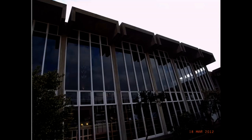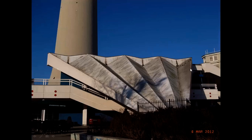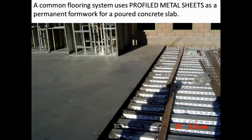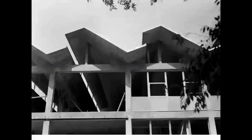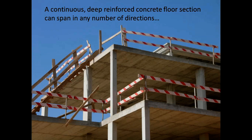So finally, all of those, as you can see, again, these are linear structures. This is spanning from one side to the other, and it's just repeated, repeated, repeated, as was our structure back at our university. If you want to build a roof and you can't necessarily take load to ground at very obvious places, you might have difficulty in bringing the load down, you will probably just do a continuous deep reinforced concrete floor section, as in this case here.